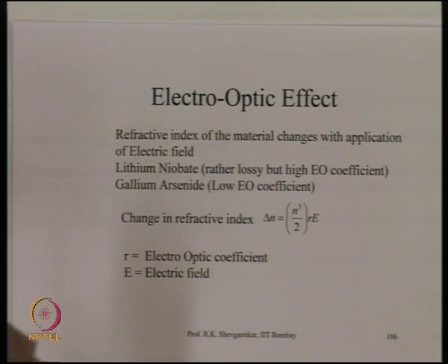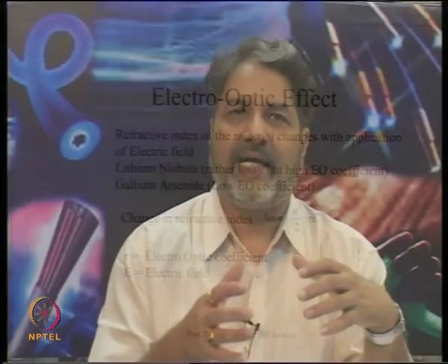This material is an anisotropic material, so the refractive index or dielectric constant is different in different directions, and when the electric field is applied, the change in dielectric constant depends upon which direction the field is applied with respect to the axis of the crystal.